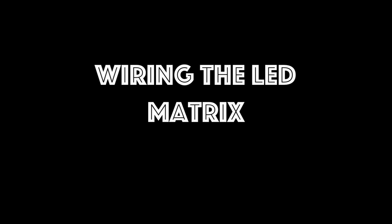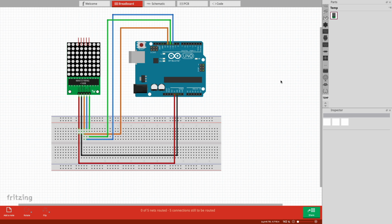So I have a wiring of the Arduino to the LED matrix. I'll have this embedded in my website along with pictures of me wiring it up. VCC, this VCC pin, and when I say pin, I mean this piece of metal, goes to 5V. GND goes to GND on the Arduino.